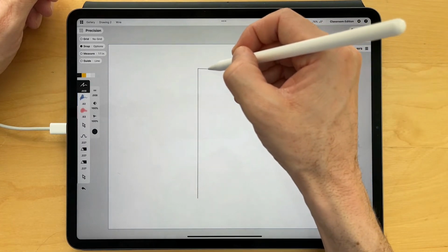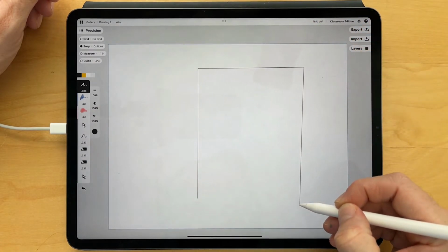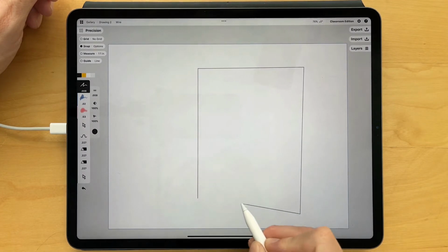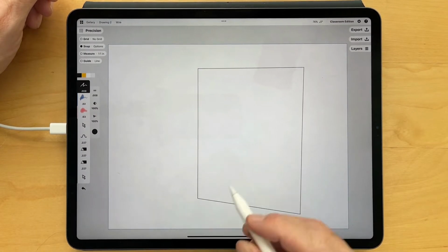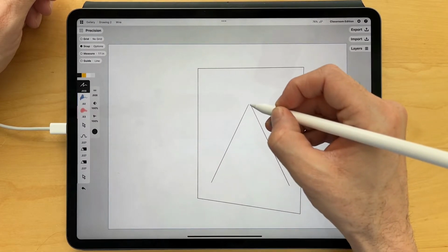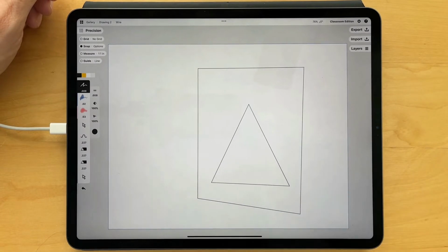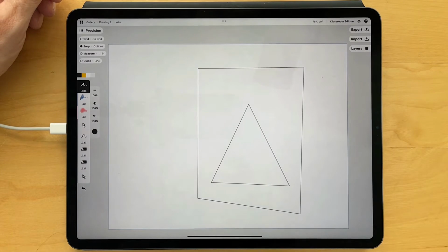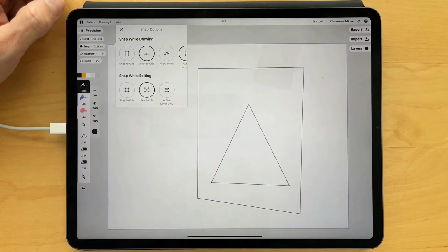Now I go to the start point and it will snap right to it. Go close to the start point, and when I start drawing, it will start drawing actually from that endpoint. Go to here, and now I get close and release, and you saw that it snapped right to it. Close. Look at that. It's so easy. So this way you really know that actually your lines perfectly are closed. Instead of zooming in and zooming out, this feature does it for me.